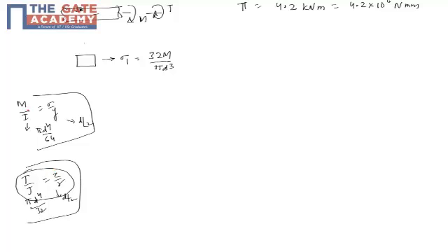These two equations are used to find this sigma 1. Now the shear stress due to the twisting is tau, and this tau value is 16 T by pi d cube. These are the basic formulas for a circular cross section. Otherwise the formulas will change, and you have to derive them from these two.